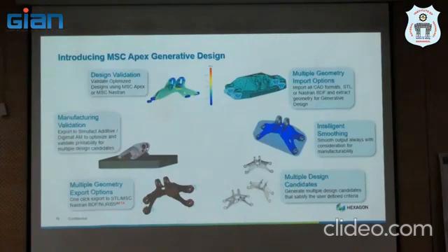So now we talk about how we print. We now understand the loading, meshing and geometry cleaning, then the topology optimization, then durability and the printability. It is not always true that any design can be easily 3D printable. It will have its own challenges when we have an internal cooling channel, or a wall thickness which is less than a particular dimension with respect to the material. There might be buckling related challenges.